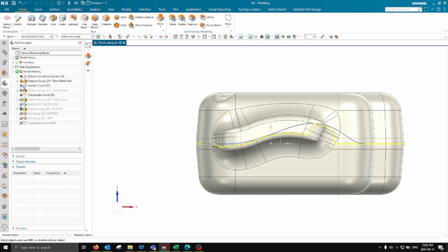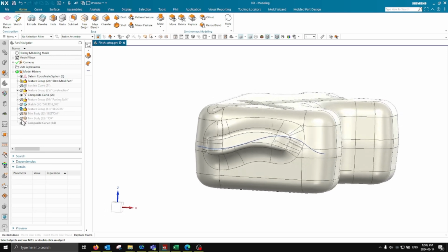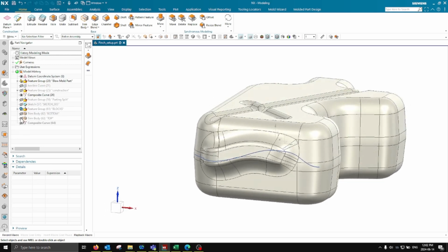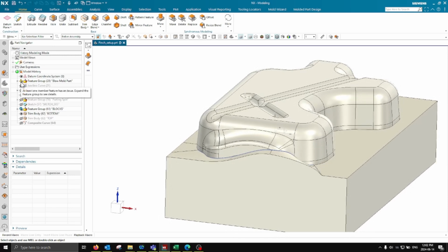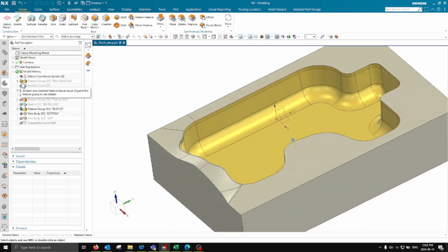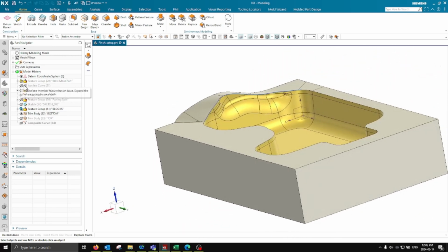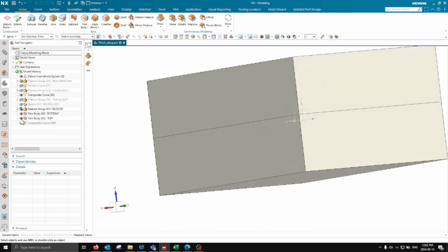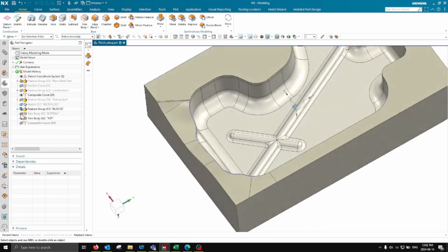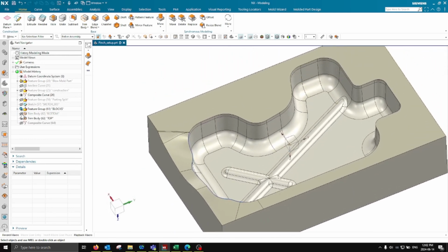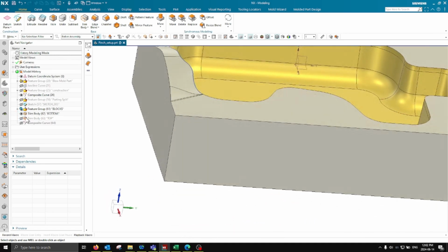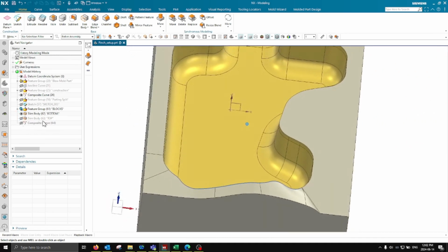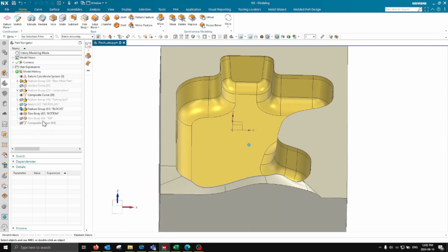We've built a runoff that's flat. And by flat, I just mean a typical flat seal-off. This doesn't have any pinch shown yet, and that's what we're going to show in a minute with the feature templates. But here you can just see our basic open-shut seal-offs. But as you know, with blow molds, sometimes you need areas that have a pinch, or in this case, multi-pinch areas to control the material closure and expand the rest. So I'm just showing the two halves here that we split with that parting line.